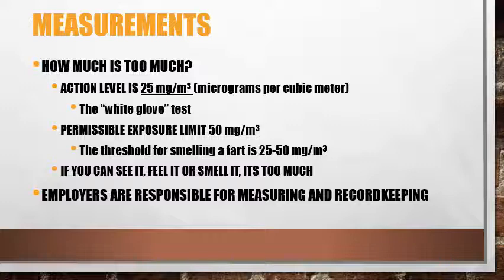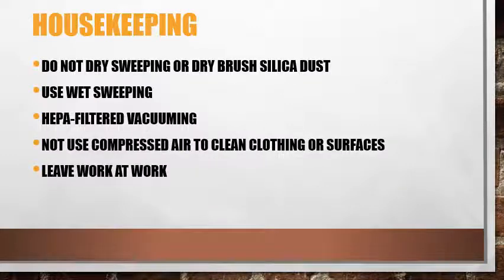So you don't even need to see it. If you can feel it, smell it, touch it, taste it, if you can sense silica dust at all, that is too much silica dust, and you must protect yourself. Employer is responsible for measuring and record keeping of silica dust levels in the workplace.